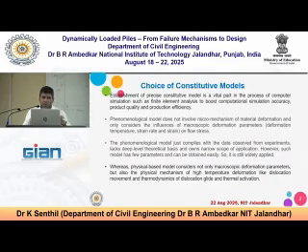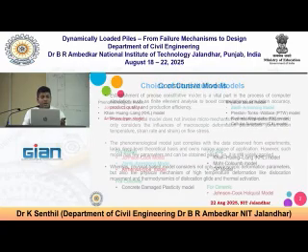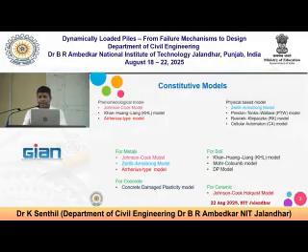So there are generally two different models, a phenomenological model as well as physics-based models. Anyway, don't go much into this material model because in structural mechanics we use slightly different models. If you look at phenomenological models like the Johnson-Cook model, KHL model, Arrhenius type model, and similarly the physics-based models, like the Armstrong model and some more models, and specifically for metals, soil, concrete, ceramic, we have different models.